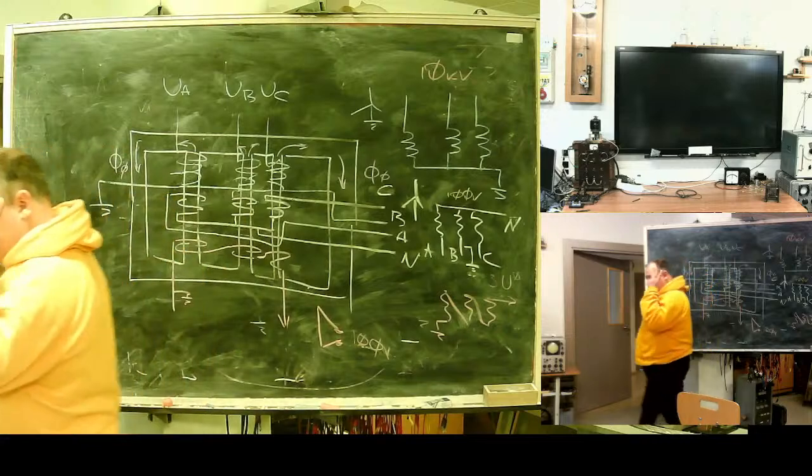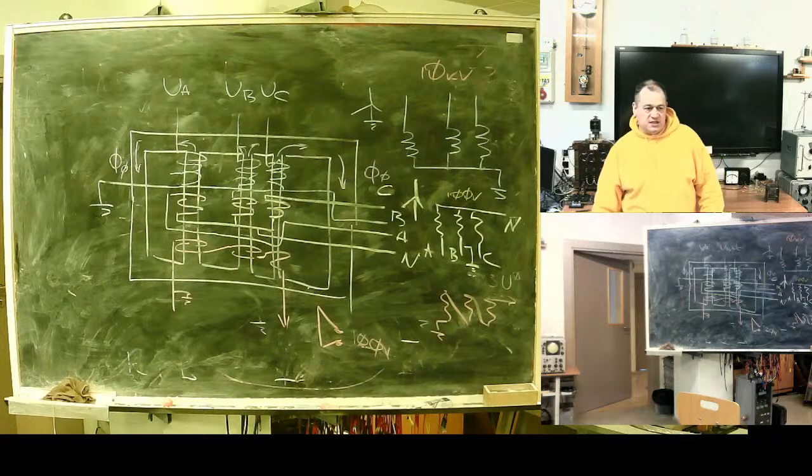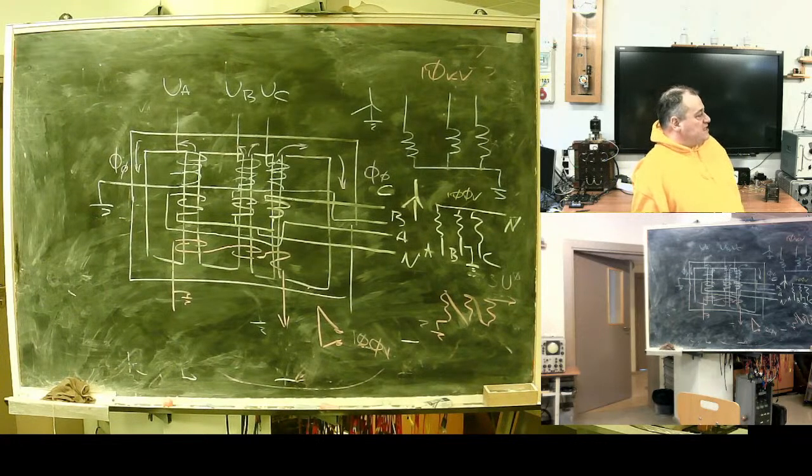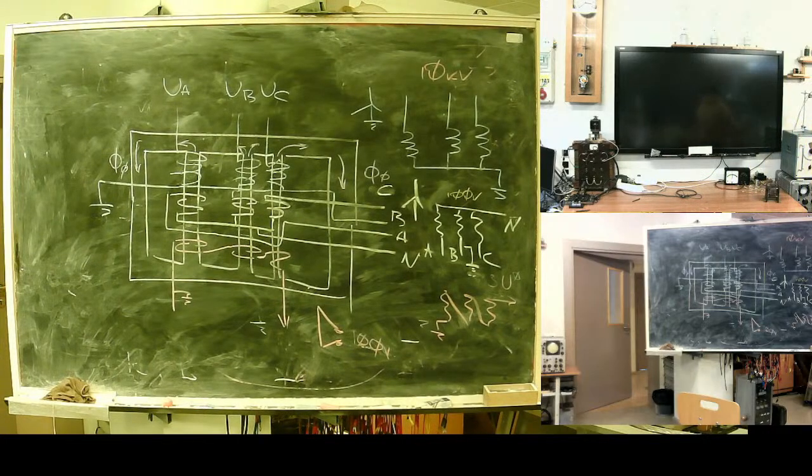Standard 3-leg transformers like this are not suitable because there is no way for the zero sequence current to be closed. They will have near zero resistance in the zero sequence circuit and will burn and blow in case of earth fault. To prevent it, a path for zero sequence magnetic flux should be provided. 4-leg is good, but 5-leg transformer.